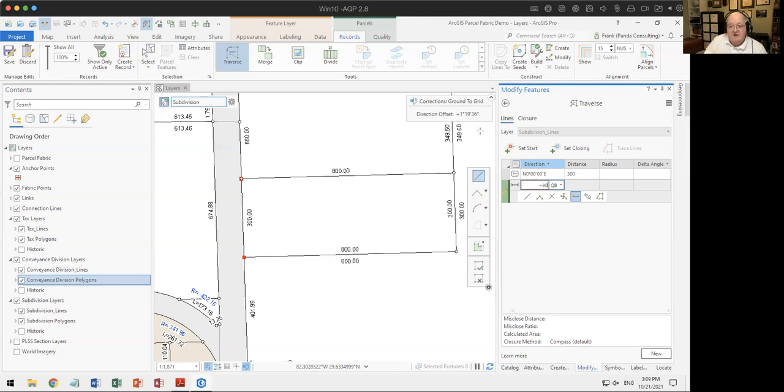Another thing I'm going to do is go due east. So I'm putting in a deflection angle instead of putting in a new bearing. So 90 degrees to my previous bearing now makes it 90 degrees north to east.